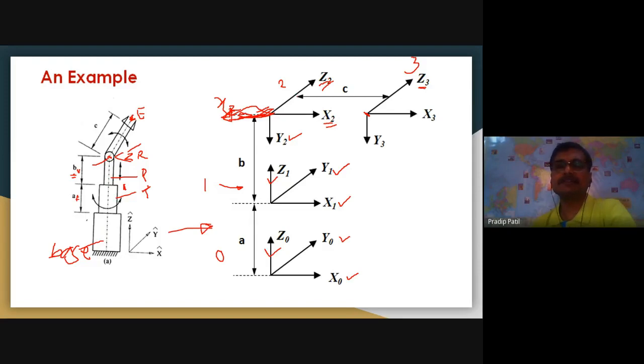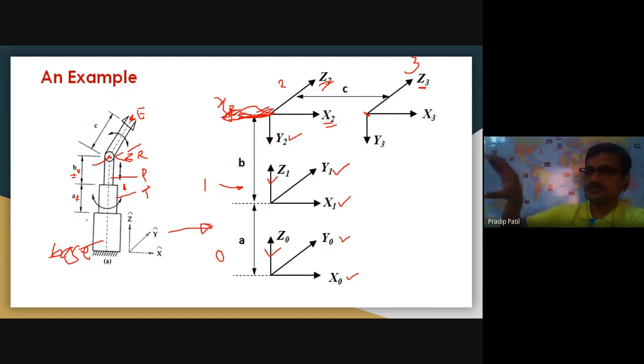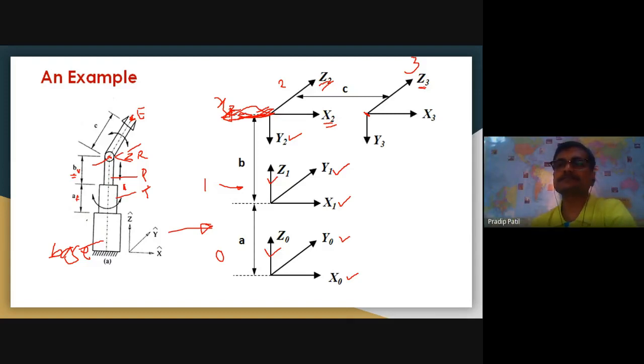Now it may happen that the end effector may not have a rotation or it will just be fixed. So we need to have just an axis for orientation. For example, I want to pick something. So for that the body frame has to be properly defined. So I just define the z-axis, z3. X I maintain the same as the earlier one, and once I know z and x3, which is the same as the earlier, I define the y3. So I have defined all these axes now.